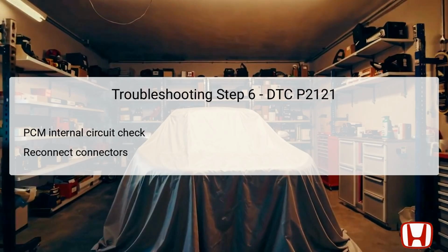Then, turn the vehicle's ignition to the on position and utilize the HDS to measure the APP sensor A voltage. If the reading is less than 0.69 volts, you have valid grounds for checking authorized service information concerning the DTCs or symptoms being faced.